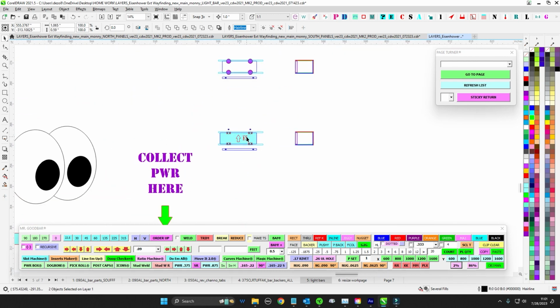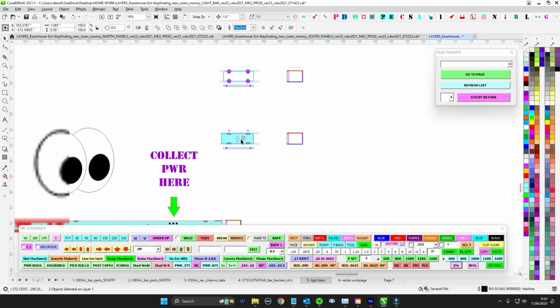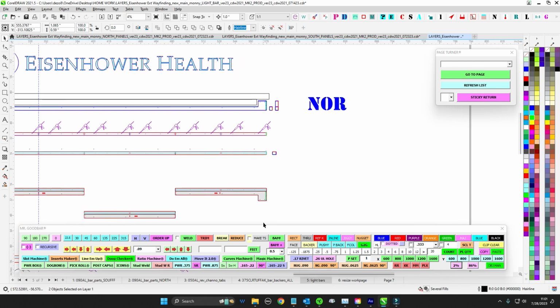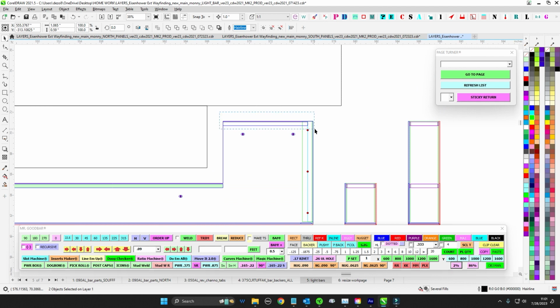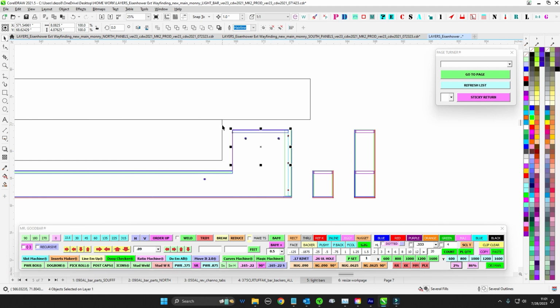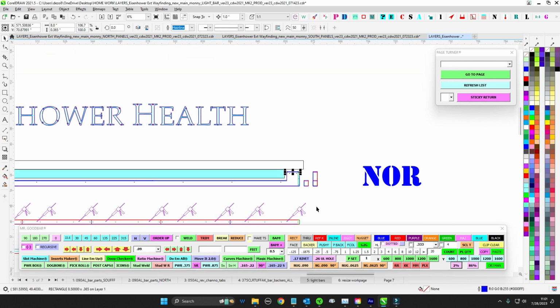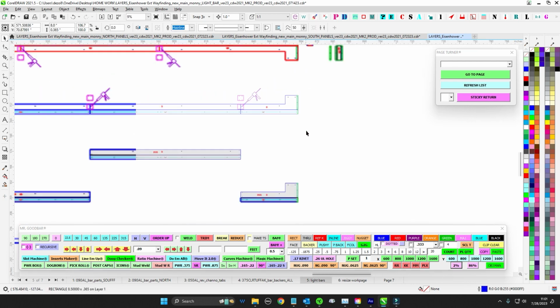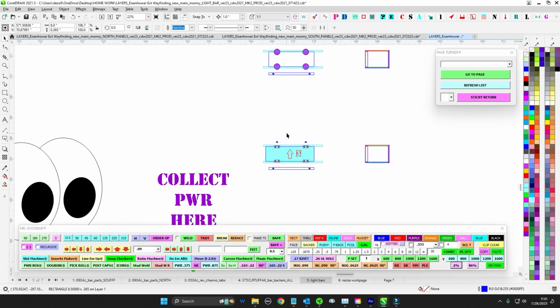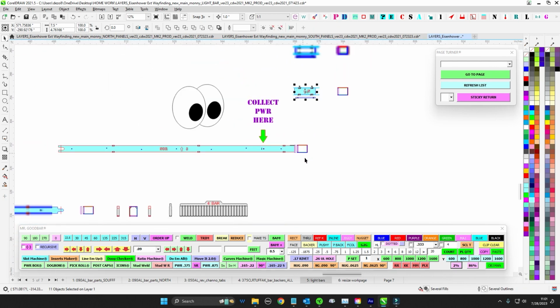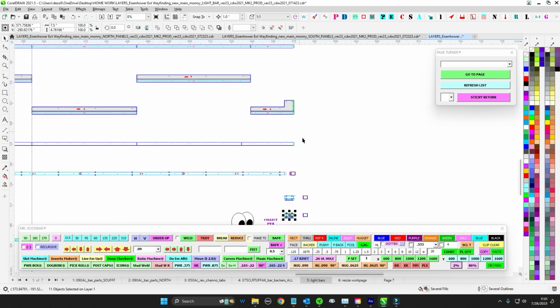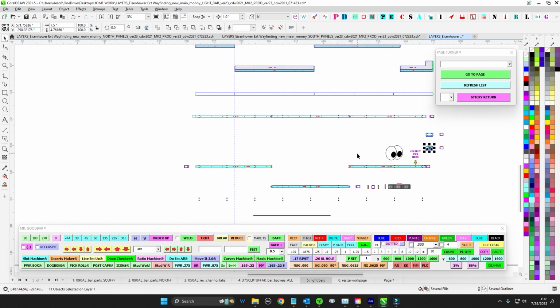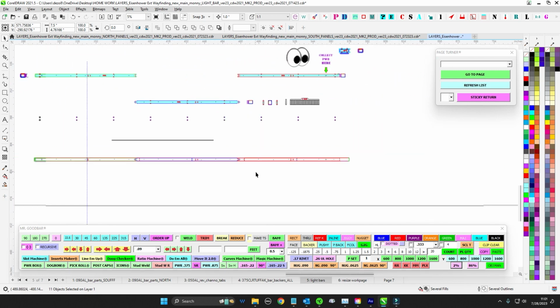And then also, this is just a little dangler piece. This does not connect to the actual sign itself. So you can see here, this is the polycarbonate for this part that wraps around the panels. Like this right here is the panel. So this part here gives that standoff. This little part just attaches, but it doesn't have any sort of wire, and it doesn't actually attach to the sign. So don't lose this little floater part, and that little floater part tucks in right there. I already have all your holes and everything ready to go, so this should be pretty straightforward assembly.